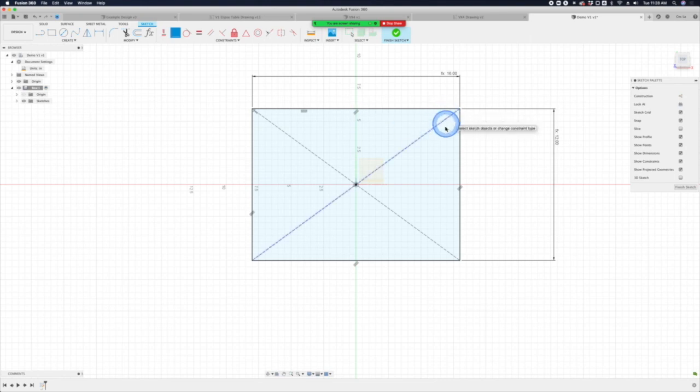Yeah, exactly. So once all these lines are black, you know that it has all the information that it needs to put all these coordinates in space, based on math, and it's not just floating anywhere. Because further down the road, if you make a change to one of these and it's not referenced by the center point or it has no real definition as to where it lands in space, it'll just kind of arbitrarily expand, and that might cause problems down the line.